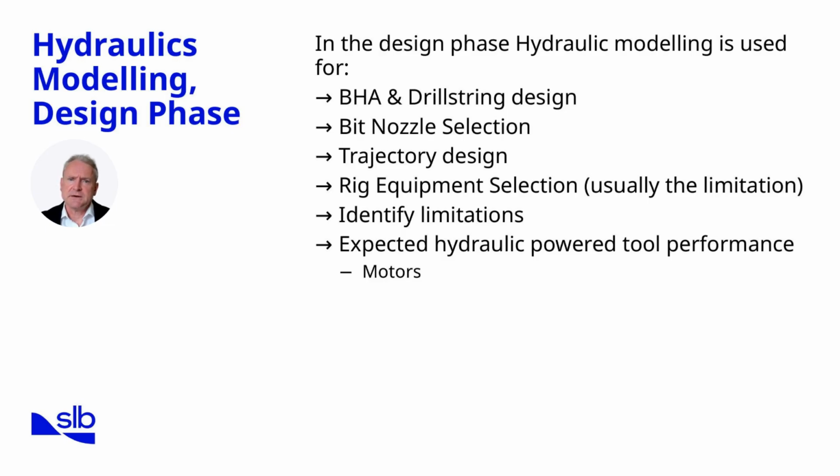Bit nozzle selection is another key application. Nozzle sizes directly control jet velocity at the bit, which impacts rate of penetration and cuttings removal efficiency. A hydraulics model allows us to balance pressure drop across the bit with annular cleaning requirements.